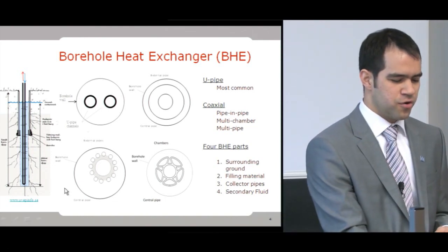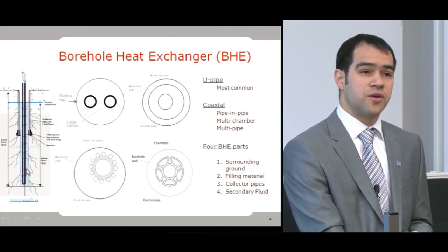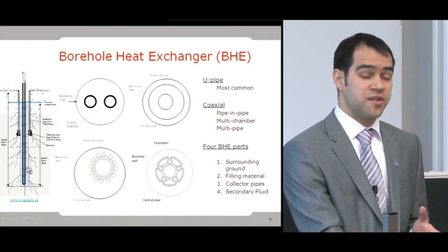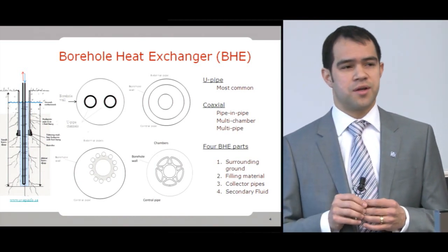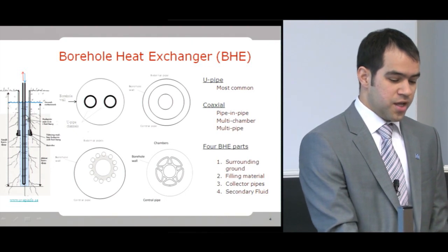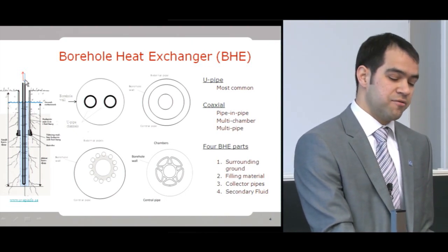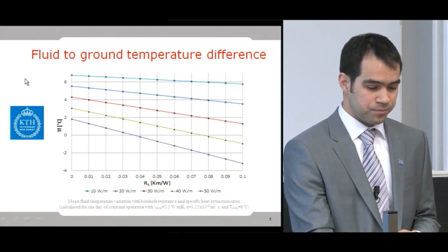and these are, of course, the surrounding ground, the filling material between the ground and the collector pipes, which in this case is groundwater, and therefore this word in my title, groundwater-filled boreholes, and then the collector pipes themselves, and then the fluid circulating inside, the so-called secondary fluid.